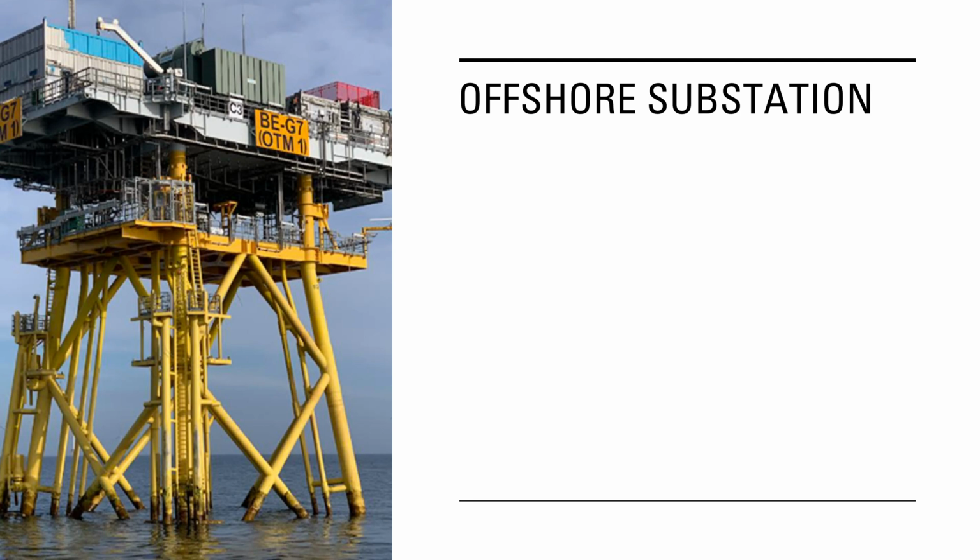Okay, let's look now at the offshore substation. Here is an offshore substation in this picture on the right. Now, this is Beatrice's offshore substation number 1. They didn't actually call it an offshore substation, they called it an offshore transformer module, because the publicity surrounding it was that it was some super slimmed down device without any superfluous equipment. But I have news for you: most offshore substations are lacking in superfluous equipment, although it is true that the bigger ones do have welfare facilities and workshops and so on.